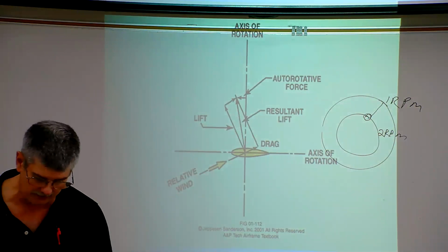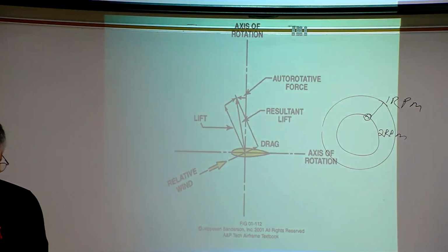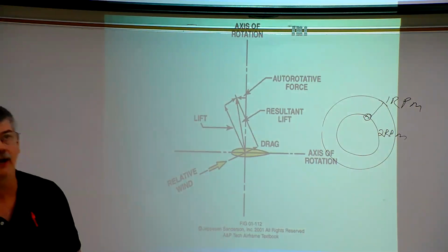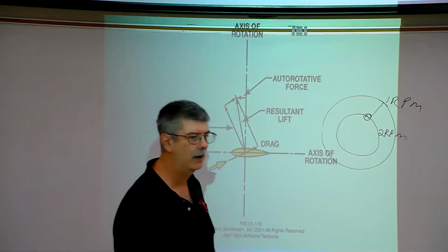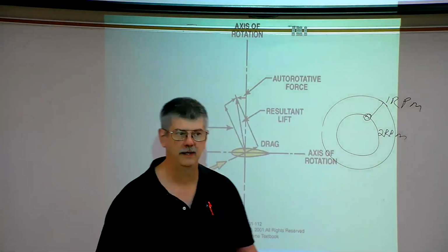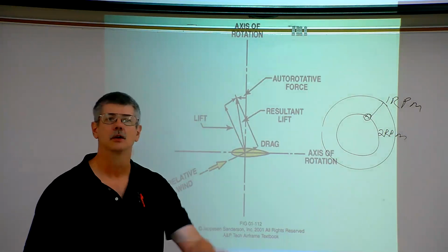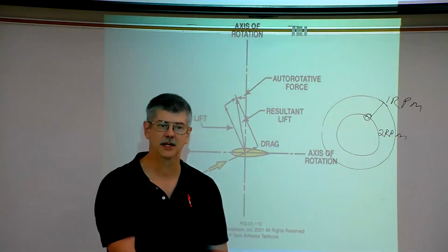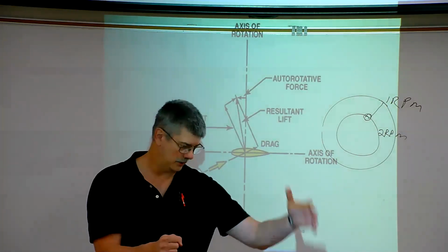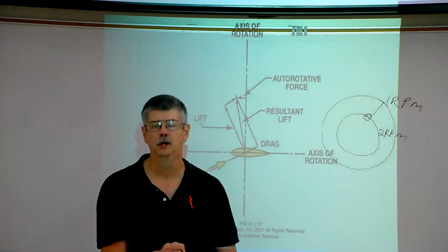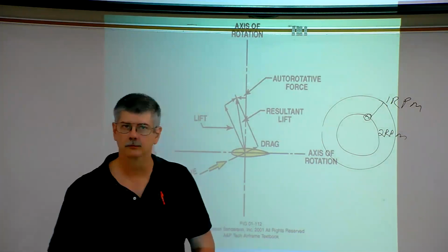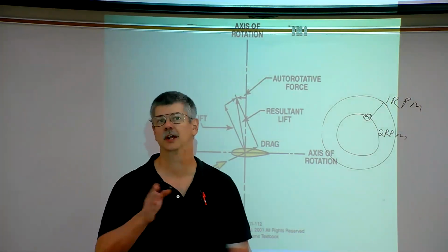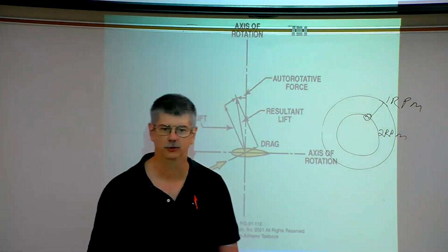What we're talking about now is what's called rotorcraft controls. How do we control a helicopter? All right, early days, be it autogyros, even early helicopters, basically there's three controls. You have the center stick, which is the cyclic. You have a side handle that goes up and down, which is called the collective. Okay, and then we have the rudder pedals that are officially known as the anti-torque pedals.